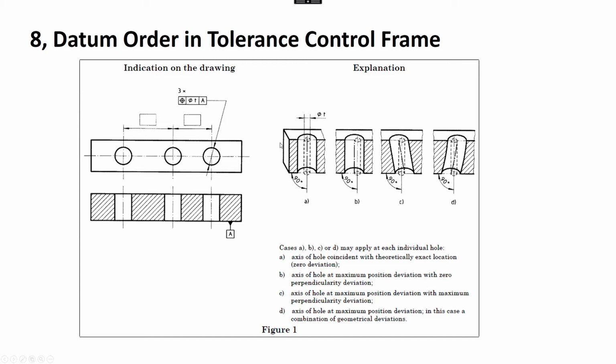So what this means really is if you've got a thicker part with the same tolerance on it, the thicker part's a lot more difficult to get right and to machine right, because if you're drilling a thicker part, your drill might wander off more. So you might have to use a different manufacturing method if you've got a tight tolerance here on a thicker part than you would on a thinner part, because the thinner part's a lot easier, because the out of squareness matters a lot more on the thicker part. So in effect, you need more tolerance on the thicker part to use the same manufacturing method.